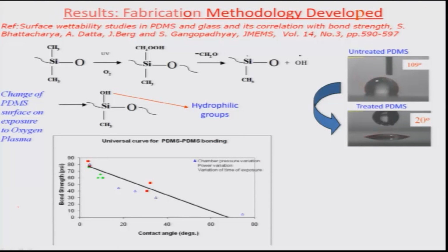In this particular slide I would like to share some of the real results which came in one of the experiments when we were trying to do plasma etching, where we would take a PDMS surface and expose it to oxygen plasma, and there would be an immediate change in the surface groups because of the high pressure low power regime which you would consider here.